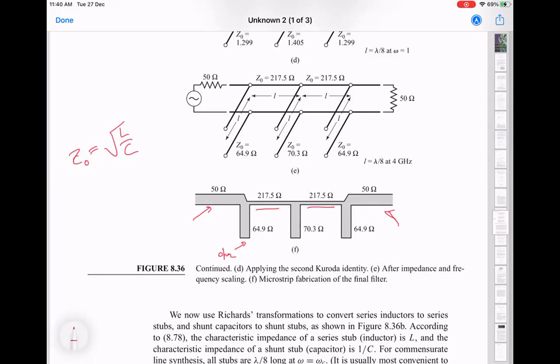So if it gets very big, and especially if it becomes comparable to the wavelength, now in the orthogonal direction, right? In the width of the microstrip starts to become comparable to the wavelength, then you have to worry about the fact that there is actually a phase change from one end to another. So that's the non-ideality that kicks in.